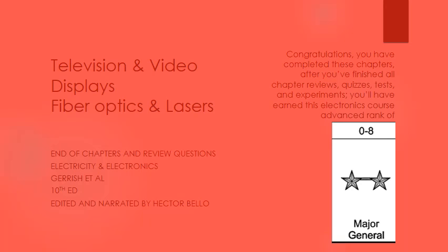Instead, modern devices use electronics to amplify the light from the moon, stars, and nearby lights. The viewing process involves 3 basic steps: focusing on a sensing screen, multiplying the electrons, and focusing the electrons on a phosphor screen. The photocathode starts the initial change, the photon energy to electron energy.